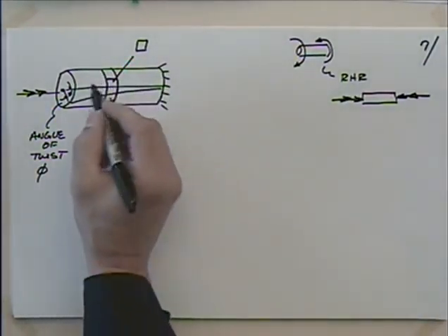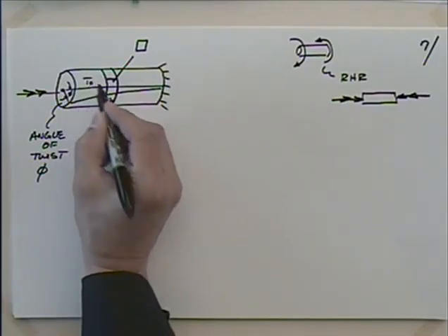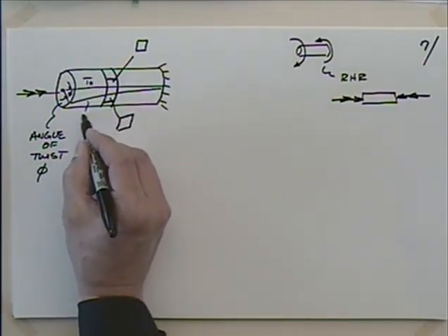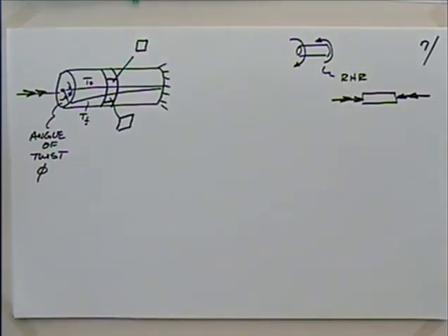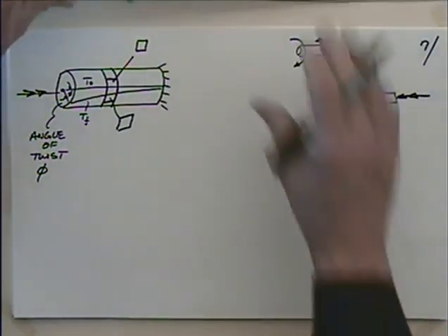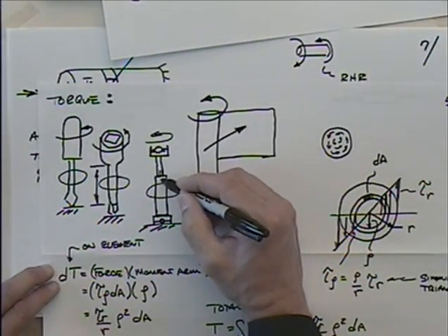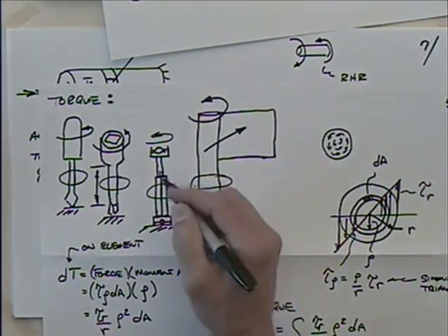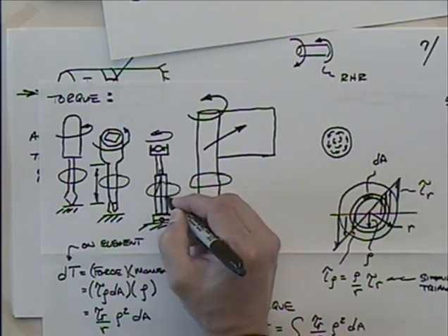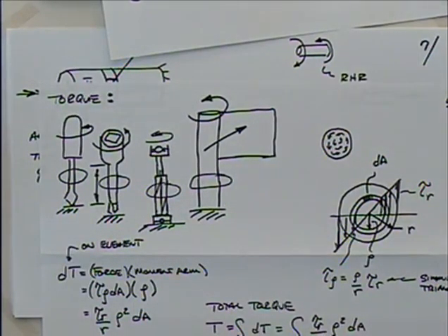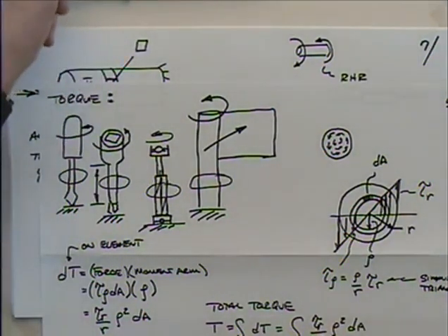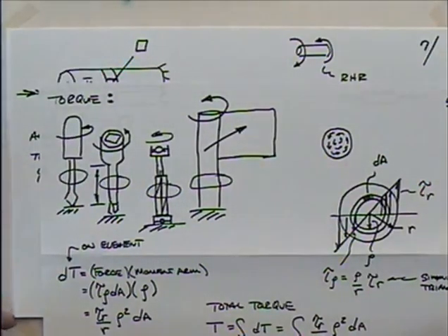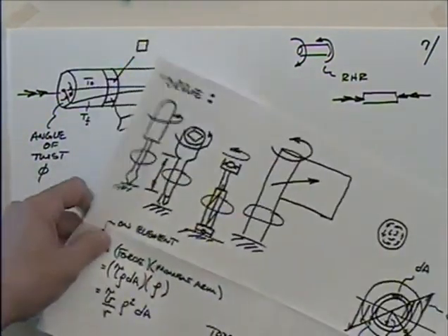So we could talk about this as a line that represents T naught. We could talk about this as a line that represents T final. Maybe you've even seen this on drive shafts. If you go to buy a car, they usually use a tubing that has a seam on it. And if the seam runs down like that, that's probably a good sign. I've actually seen drive shafts where the seam went around this thing. That means it was probably not just driven to church on Sunday, if they've twisted the drive shaft that much.